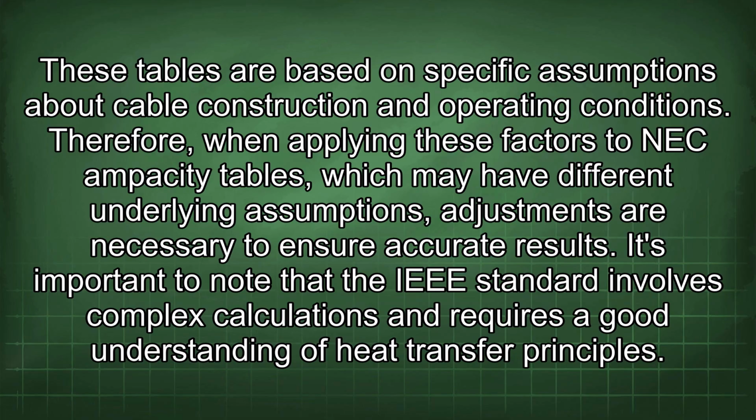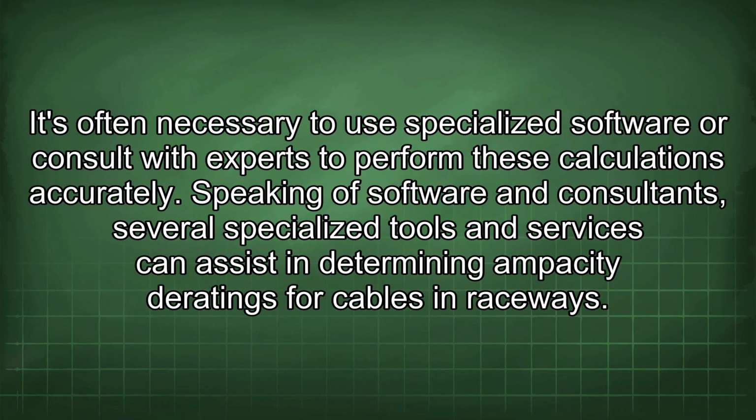Therefore, when applying these factors to NEC ampacity tables, which may have different underlying assumptions, adjustments are necessary to ensure accurate results. It's important to note that the IEEE standard involves complex calculations and requires a good understanding of heat transfer principles. It's often necessary to use specialized software or consult with experts to perform these calculations accurately.